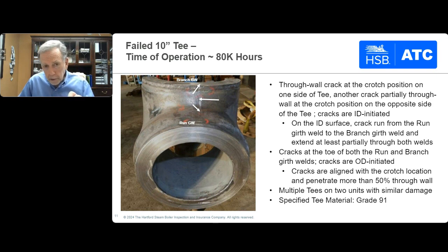There was something a little peculiar about the crack profile in both cases, though, which is directly related to some of the design-related issues that Jay will talk about later. And that's the fact that normally when you see a crack that propagates through a relatively thick wall component, propagates through for a good percentage of the wall thickness, there'll be a proportionality between the extent of the crack on the OD surface, if it's starting from the OD, versus the depth of penetration.